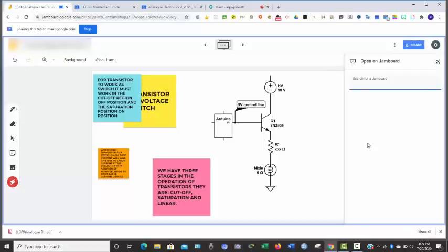And if you remember what we have as efficiency, under efficiency we have what is called work output over work input. That principle is the same for anything we are looking at as efficiency or gain in physics. So in the case of a transistor, the input in this case is IB. IB is our input, and our output in this case will be our IC, because we are feeding in IB, and what will be the result at the collector current,